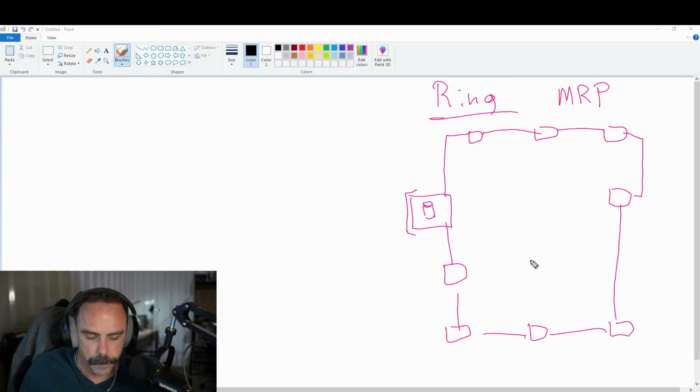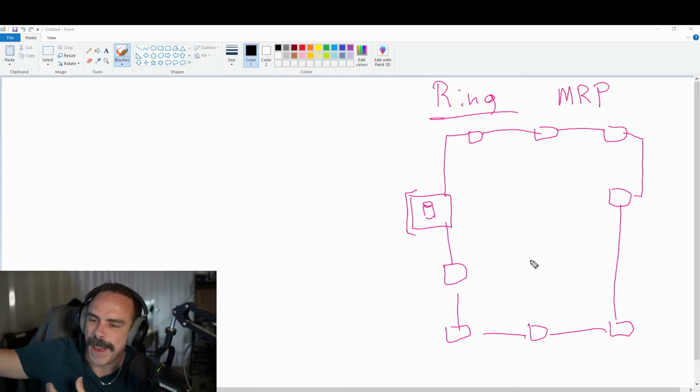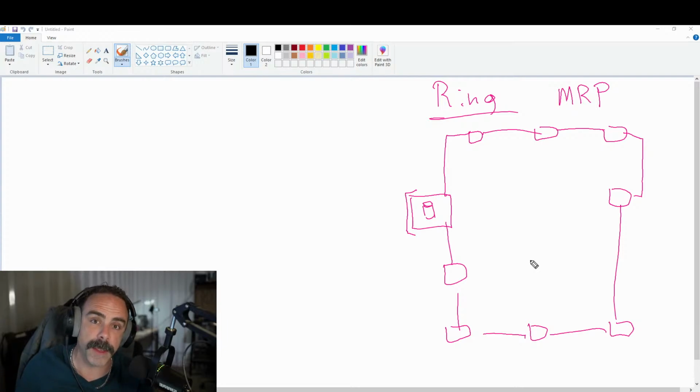But with a ring manager, obviously the biggest thing here is how far these connections are. In an office environment, you're talking inside of a few hundred feet. Well, in the plant that we just started up this past year up in Wabash, you have almost, I would say, 700-800 feet between some runs. So you just physically cannot use copper Ethernet on that. So you would have to run fiber for those runs.